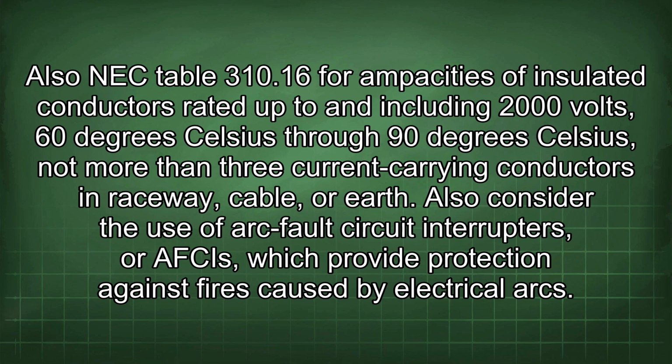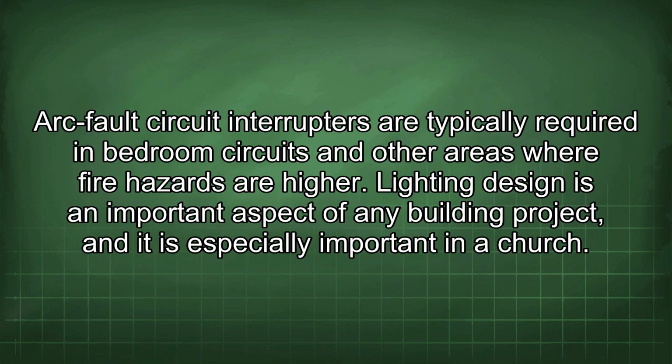Also consider the use of arc fault circuit interrupters, or AFCIs, which provide protection against fires caused by electrical arcs. Arc fault circuit interrupters are typically required in bedroom circuits and other areas where fire hazards are higher.